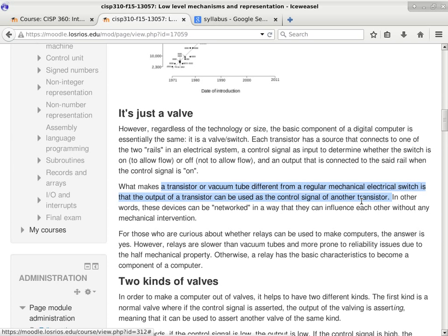The battery? You're getting close. It's not a battery. Oh, the rotary. Obviously, you guys don't have a whole lot of automotive failures, because this is an item that fails quite often because of the mechanical aspect of this device. It's a relay. What is a relay? A relay is a switch. You can use it to close a circuit. You can put a load and have it switch the circuit.